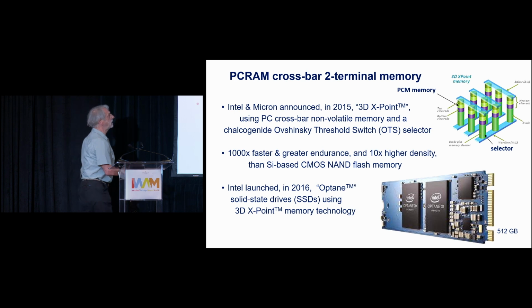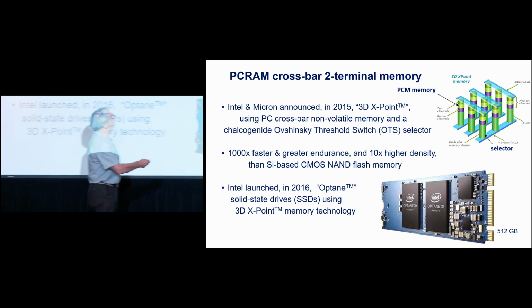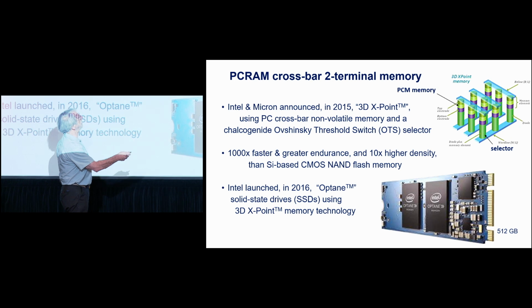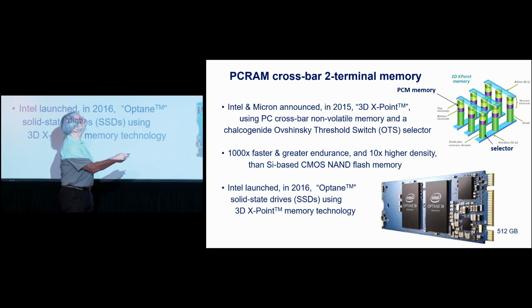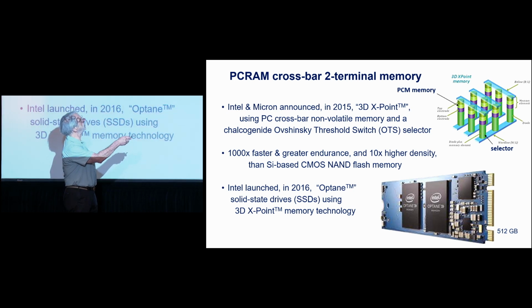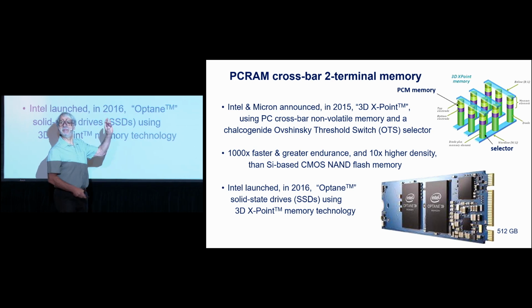And here they are in a 3D cross-point array. So these blue lines are electrical conductor lines. These are the word lines, and these are the bit lines. So you apply voltages to the blue conductors here, and then if you've got a selector switch here, which I'm going to talk about a bit later on, you can switch on or off individual pixels, individual memories.